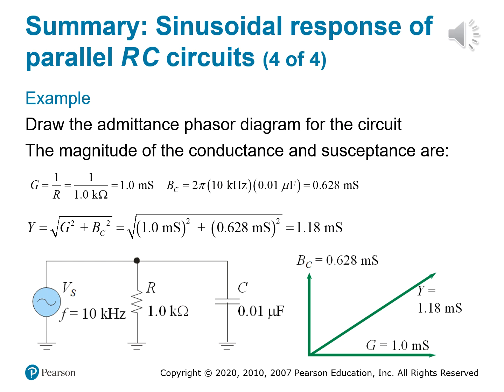And you're right. It parallels the parallel RL triangle, but just rotated, right? Because inductive susceptance is negative and capacitive is positive. And again, this is more geometry, and this is why, no, I won't say anything about geometry in high schools, other than it's needed. It's a way to predict circuit behavior at a glance, just by looking at it.